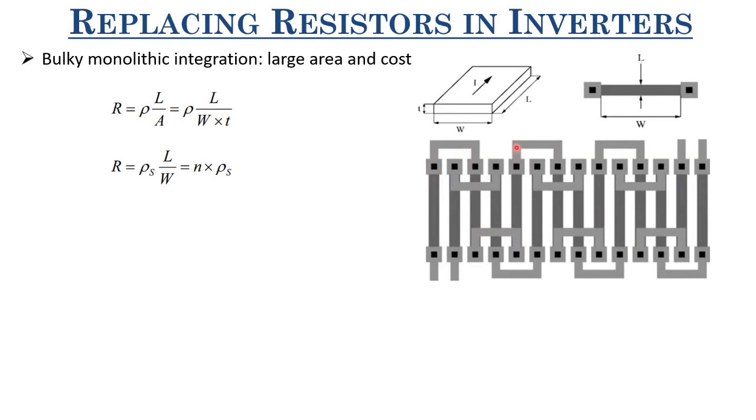of these alternate pillars, or I would say alternate individual resistances? Because these alternate resistances would be very closely matched to this one. This would be very closely matched to this one. So if you are choosing or connecting alternate resistances, overall the matching would be better. So the ones which are in the neighborhood are perfectly matched.